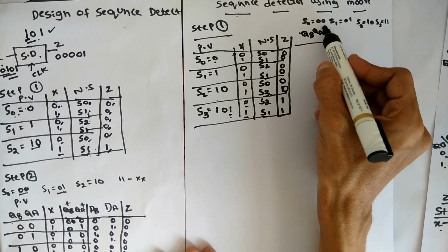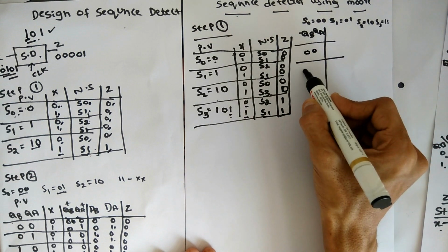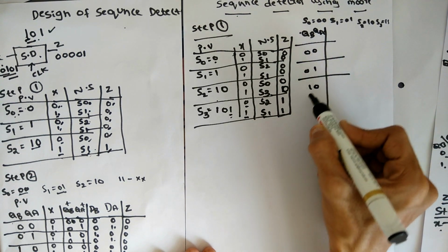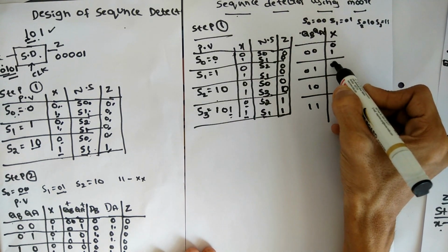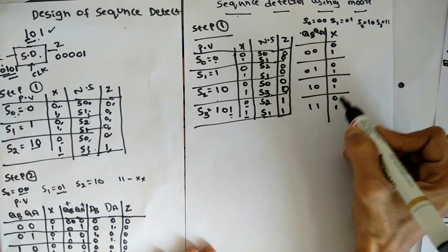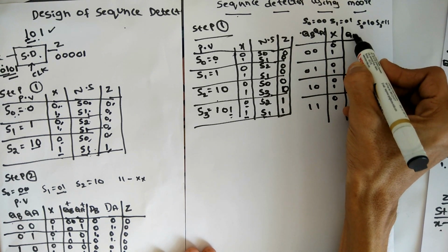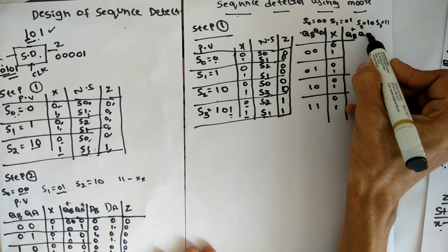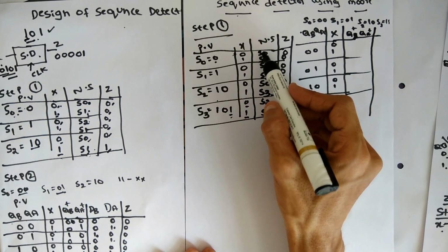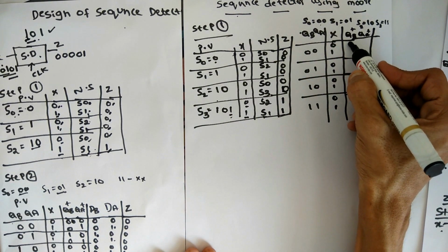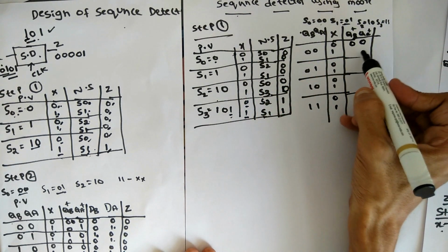So the first state we can call A, that is 0 0, and then 0 1, then 1 0, then 1 1. So X is the input, with two possibilities, 0 and 1, and the next state is what we have to write. So we can write QB plus and QA plus. Check with the states in the previous part. Here S0 is there, the first one, S0 is 0 0, so copy down 0 0. S1 is nothing but 0 1 from this, so 0 1.